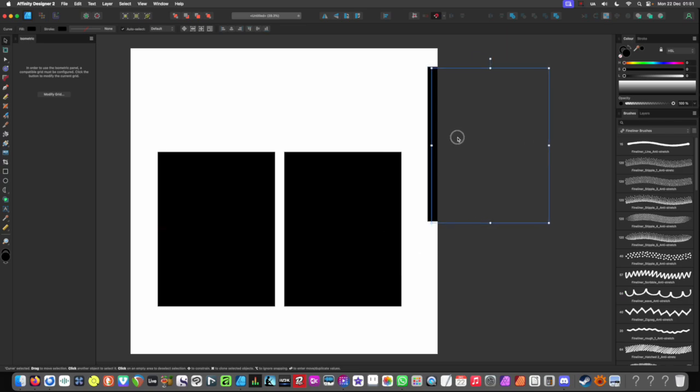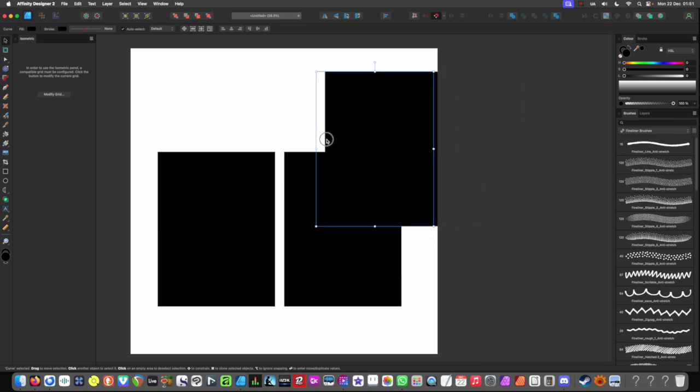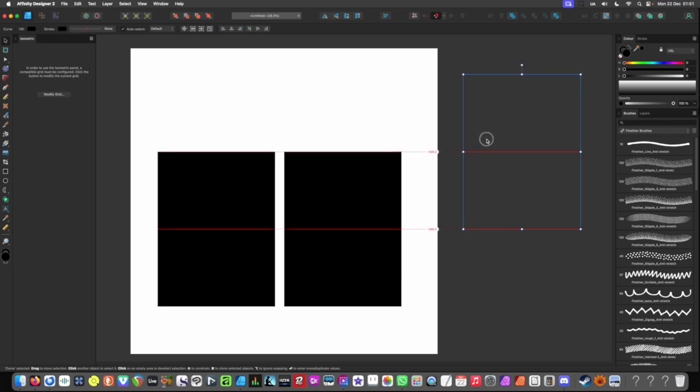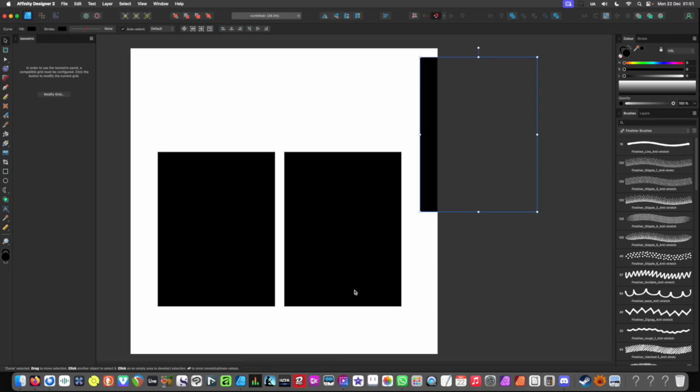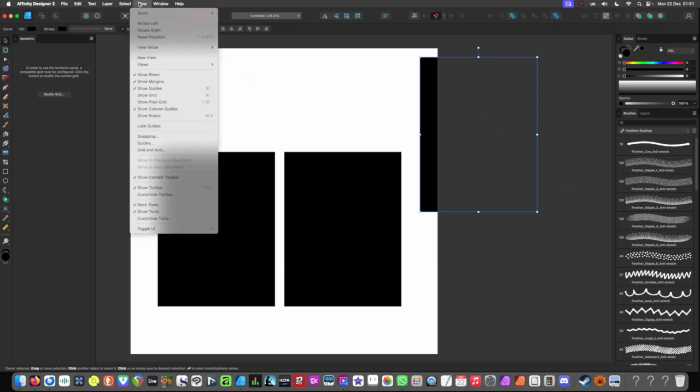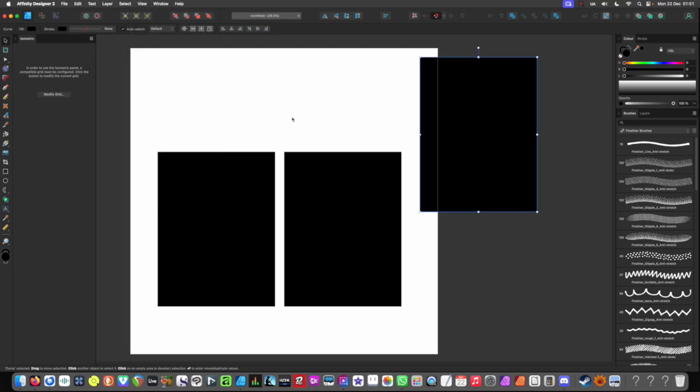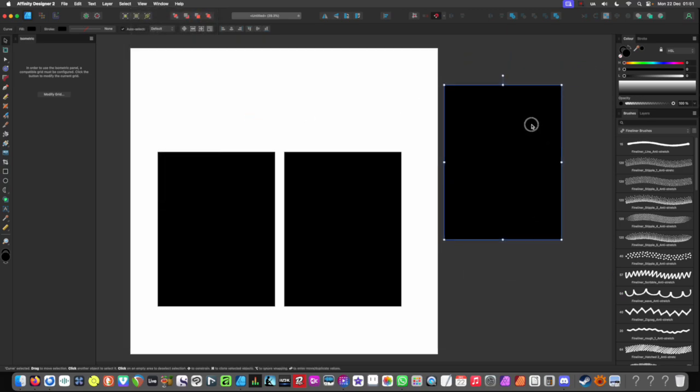Now this is annoying. This sometimes happens, where I like to have the outside of this area as a sketch pad where I can leave little bits. It took me a while to figure this out, believe it or not. It's called Clip to Canvas, which is on, and I don't know why, because usually I have it off. If that ever happens to you, go to View Mode, Clip to Canvas, turn it off, and now we can have our little extra asset here.